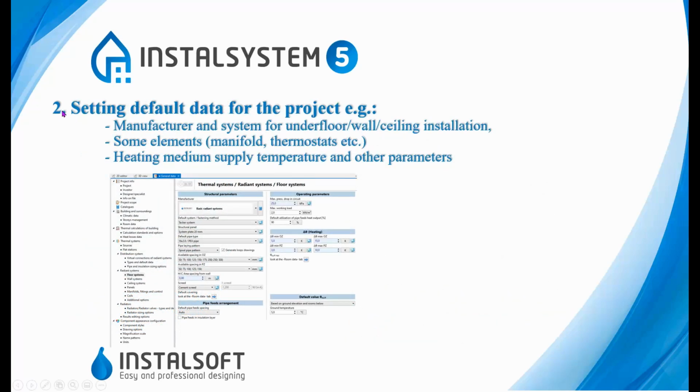Stage number 2, setting default data for the project. Using some window in the program, it's called general data, you can enter, you can modify, or just browse some general data for the project. Like you can choose manufacturer and the system for underfloor, wall or ceiling installation. You can choose some basic elements like manifold, thermostats, and you can set the most important parameters like supply temperature, temperature drop, maximum pressure drop.